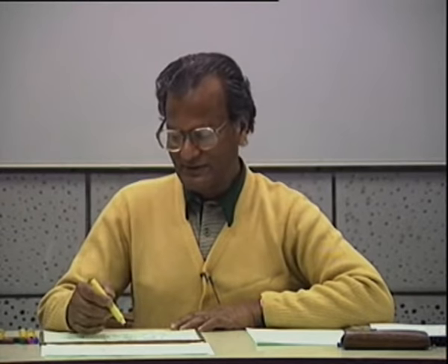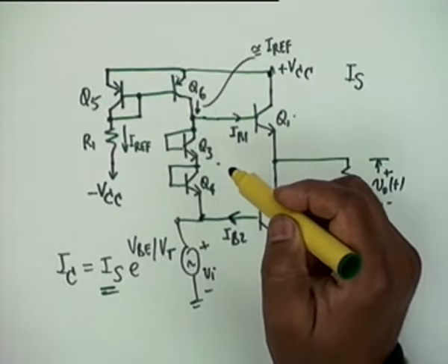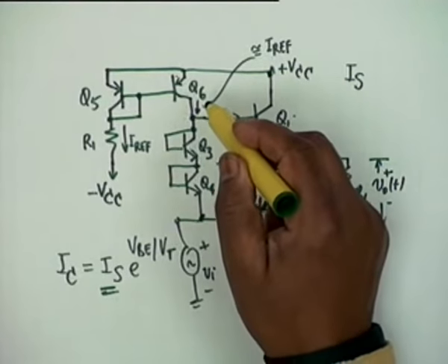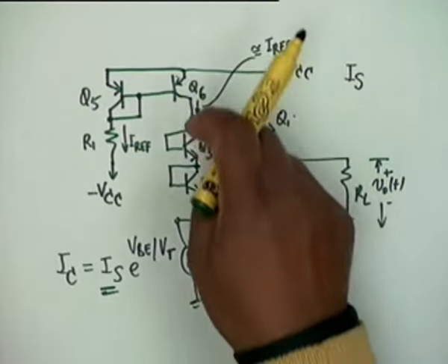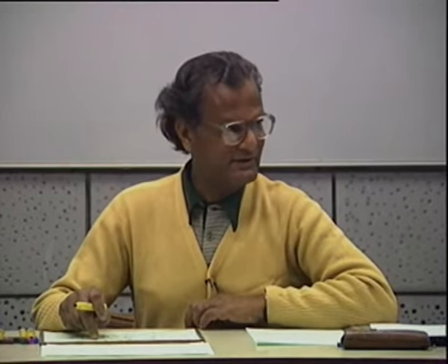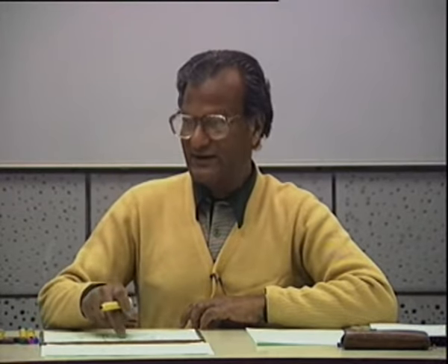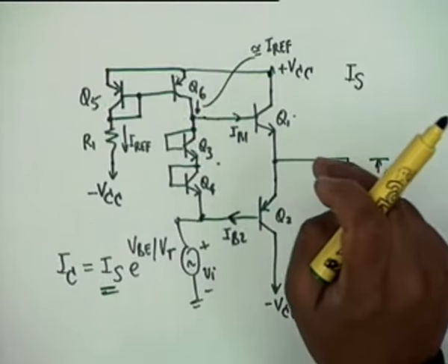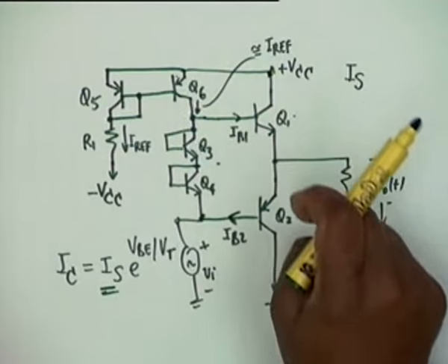There are 4 transistors here. If you can reduce the junction area to 1/4, then this would be equivalent to fabricating 1 silicon transistor of a larger capacity. Agreed? So IS3 and IS4 would be much smaller compared to Q1 and Q2,